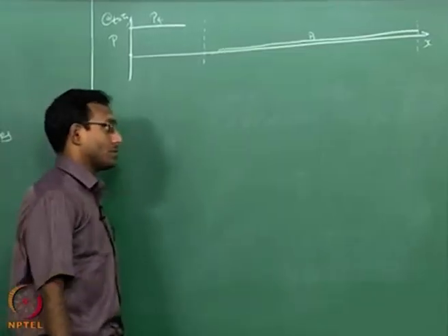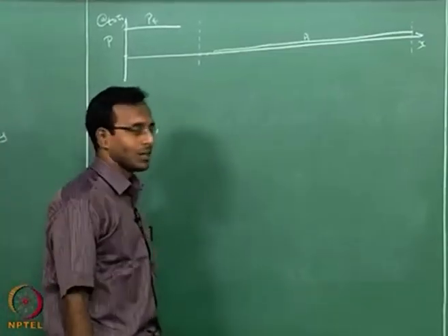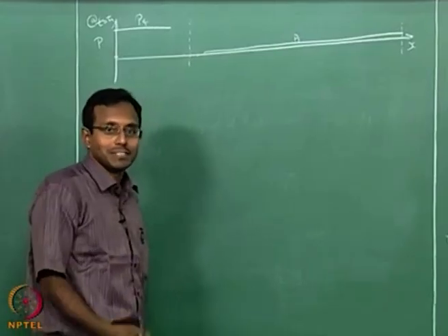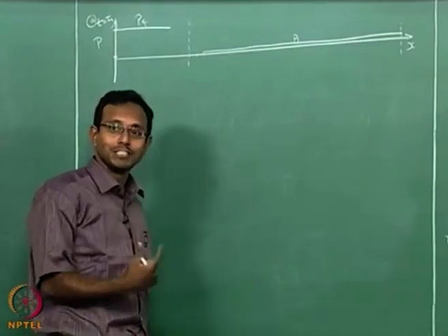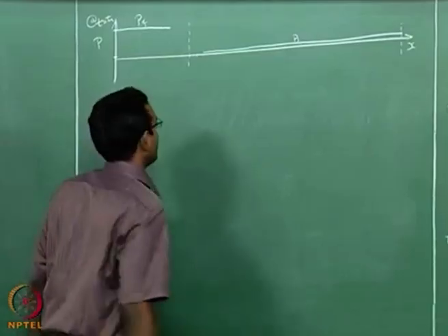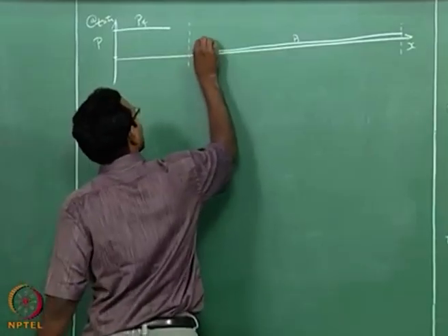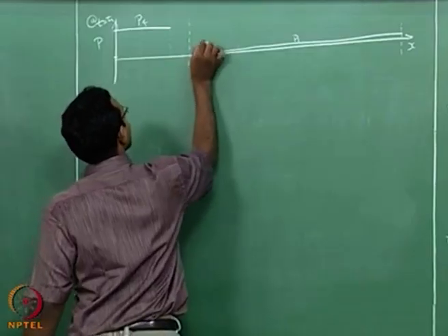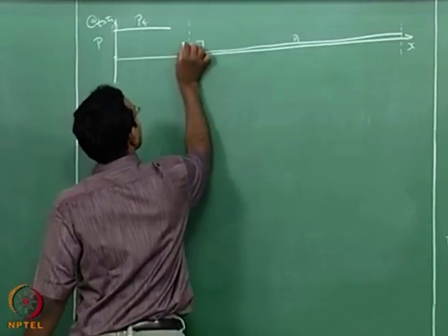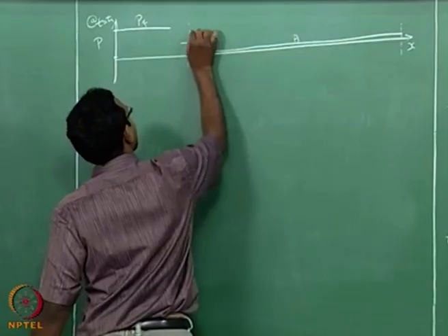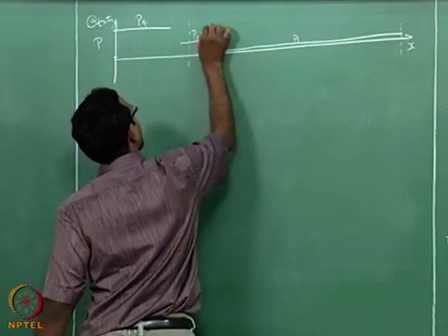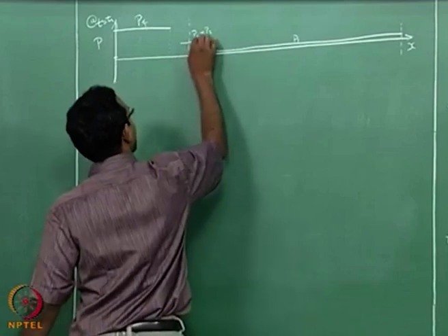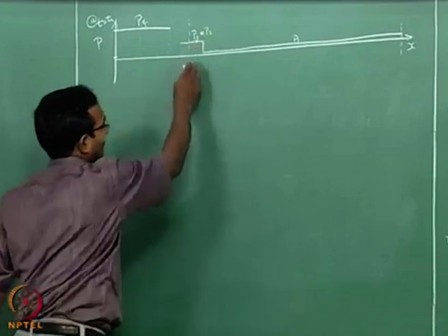Now we know after the shock the pressure goes up, but it cannot go more than P4, right? It has to be something in between P1 and P4, because P4 is the one which is causing the shock. So it will be something intermediate, and then I know that is the P2 value, which is same as P3 value, goes all the way till there, P2 equal to P3. This is what is happening there, and this particular location is the contact surface location.